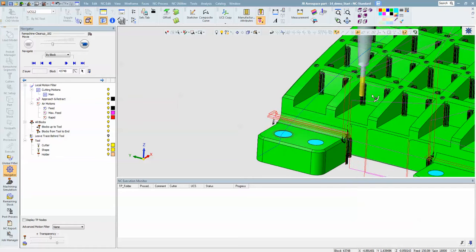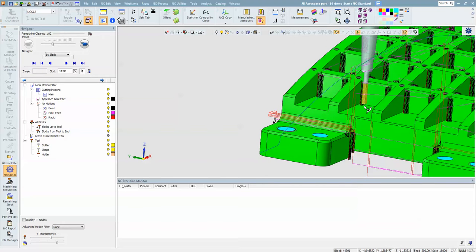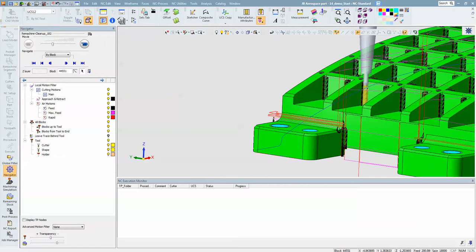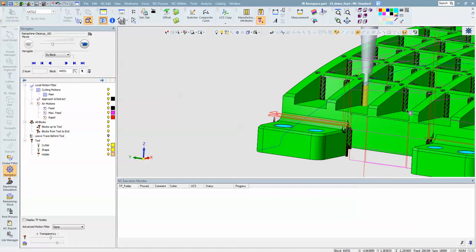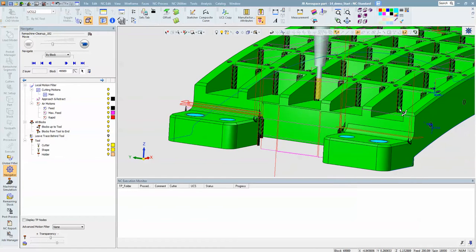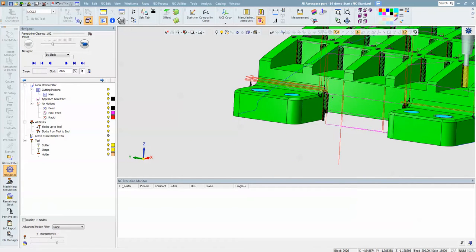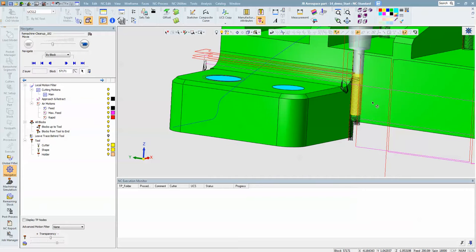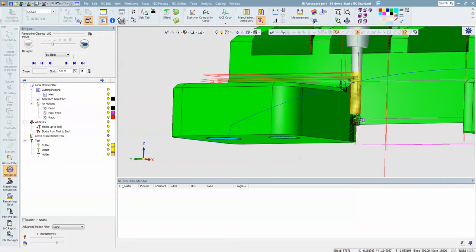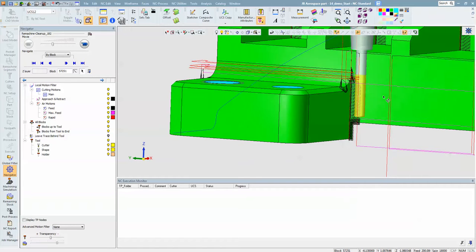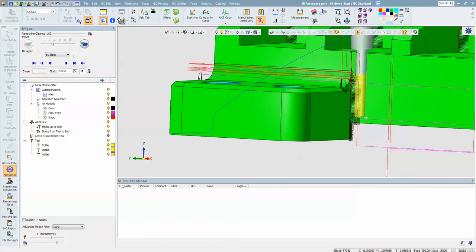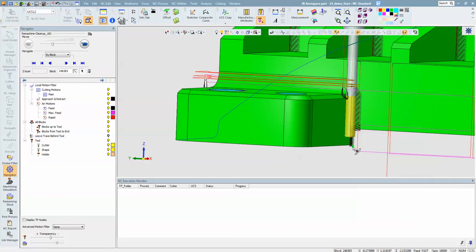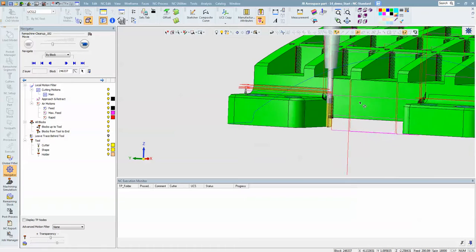So here's a 1/8 cutter, where that length of tool is good for probably 99% of the job, but there's a couple areas where that length is too short, and so it takes it down as far as it can, just about where the tool holder would start colliding, and then it's capable of grabbing a longer cutter and going in and finishing those lengths. And it does that automatically in the software. It's a very nice feature.